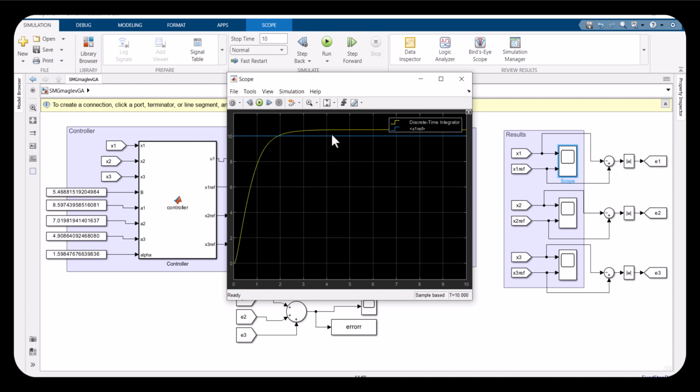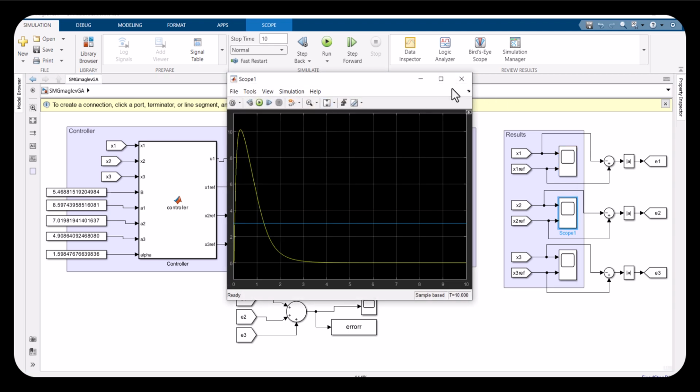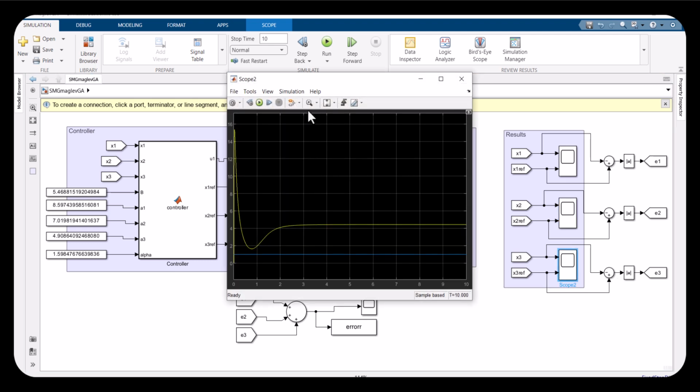And we do have a steady state error, but that would be resolved using integral sliding mode control. That's a different controller, but using this same controller we got a better performance than before by using optimized gain values. Here you see again we go to the final value at an earlier stage, here as well at an earlier stage.